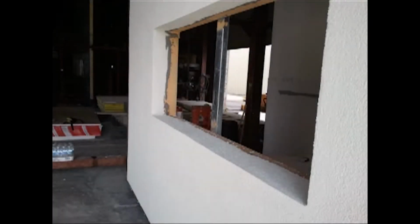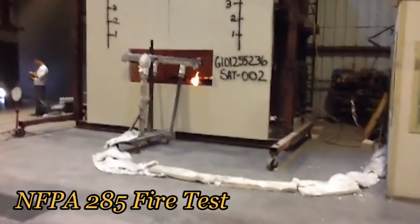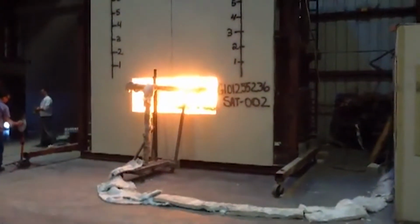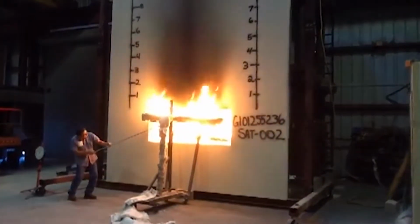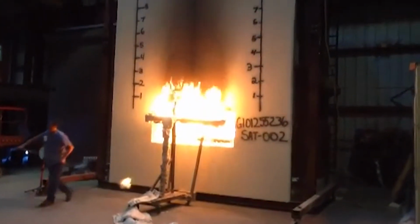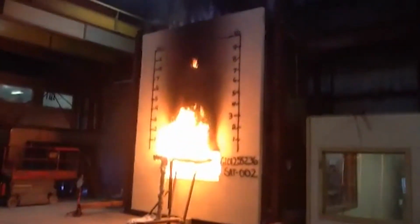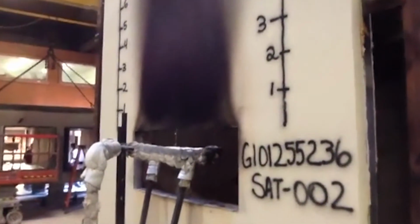For exterior use of FRP over 4 stories, passage of the NFPA 285 multi-story building test is required. This test requires a full mock-up of a wall section be tested by an open flame exiting a first-floor window on the exterior of the mock-up. The mock-up must survive a 30-minute fire. This test is difficult and expensive, and to date, few composite wall systems have been approved.